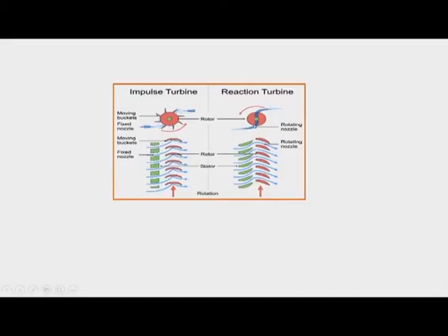Similarly, in the case of the reaction turbine, we have green as the nozzle and red as the turbine blades, and the dynamics is the same as the sprinkler, where a jet comes out in one direction and as a reaction the rotor rotates in the opposite direction. The nozzle passes a low pressure, high velocity flow toward the turbine blade, but here the movement of the flow in the turbine blades is smooth, unlike in the impulse turbine, where there is an abrupt change in the streamline pattern.